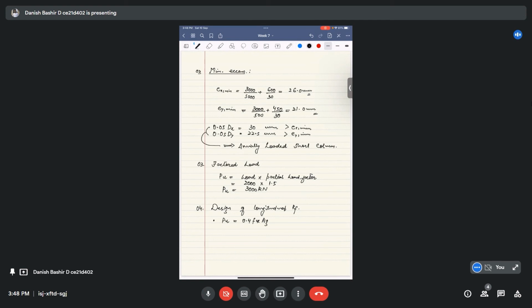This formula is discussed in detail in the lectures available on the portal. It is simply the load carried by the concrete present in our column section, and the load shared by the reinforcement, where Asc is the area of the compression reinforcement.